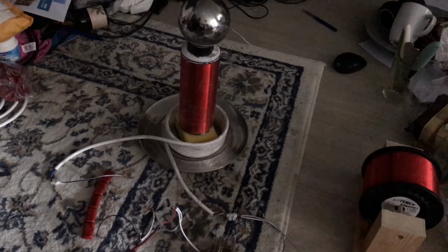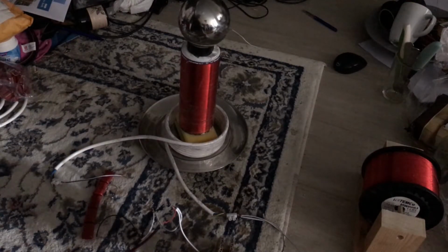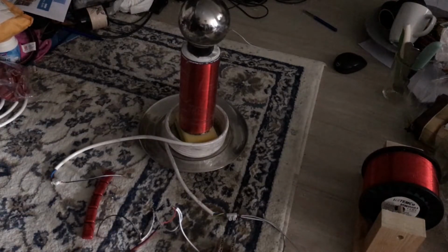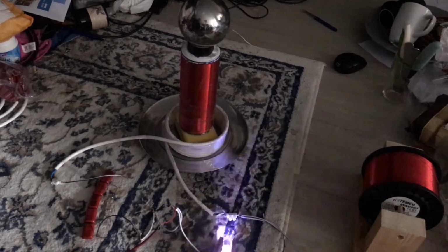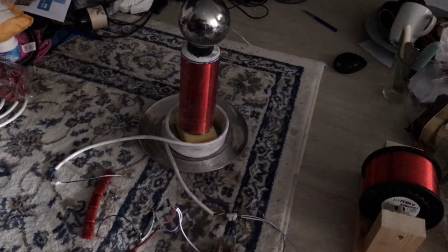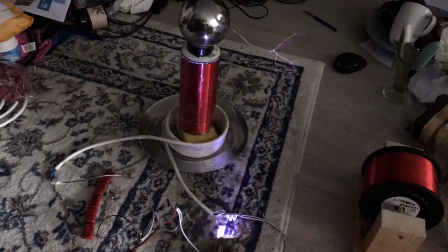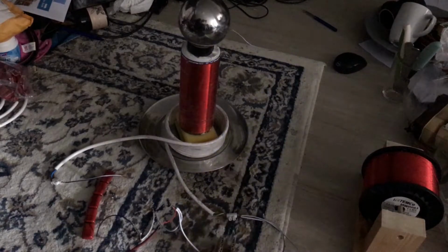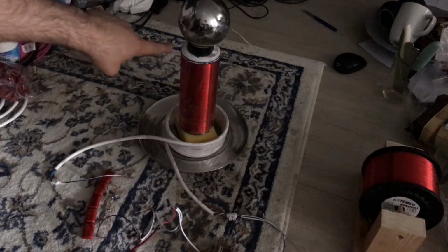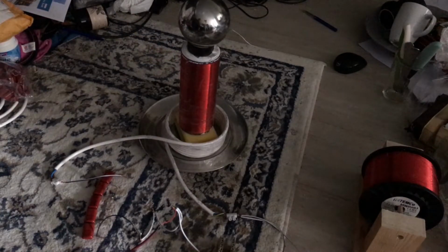Of course, the discharges are not very strong because we have some light in this room, so you will not be able to see them properly, but now I increase the gap distance a bit, and hopefully the discharges will be more visible. If you pay very close attention, you can see that there are some discharges also from these regions, which is really not desired.